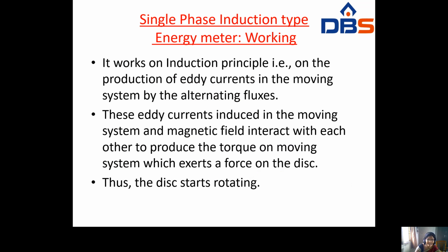Coming to the working, now we discuss the working of the single phase induction type energy meter. It works on the induction principle, that is, on the production of eddy currents in the moving system by the alternating fluxes. Induction means whenever current passes through one coil, it produces flux. That flux will be linked with another coil. That is nothing but the induction principle.